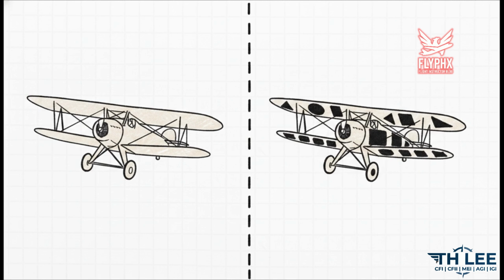But listen closely, fellow aviators. These historical exemptions vanish in an instant the second you penetrate an Air Defense Identification Zone, an ADIZ, or a DEWIZ, a Distant Early Warning Identification Zone. National security immediately trumps historical aesthetics, and you must display full 12-inch compliant marks in those airspaces, no exceptions.